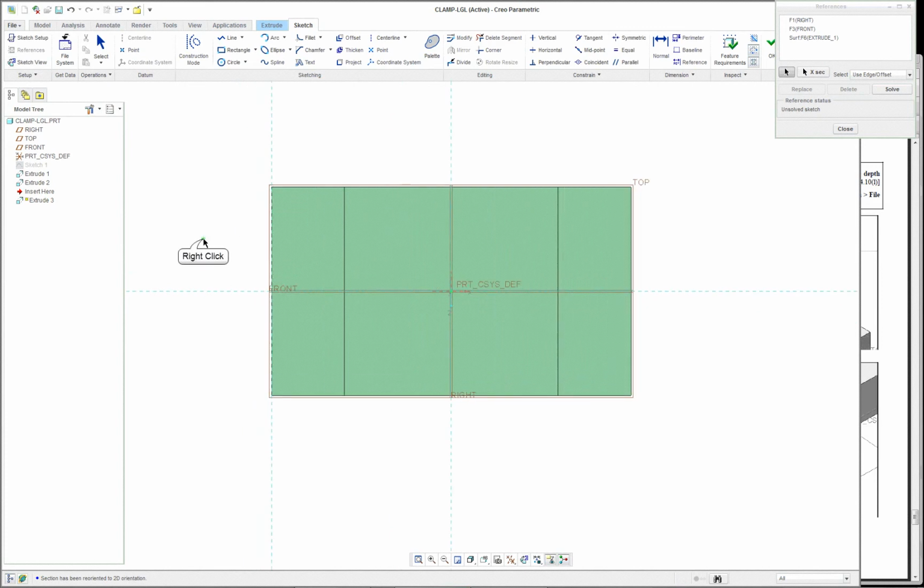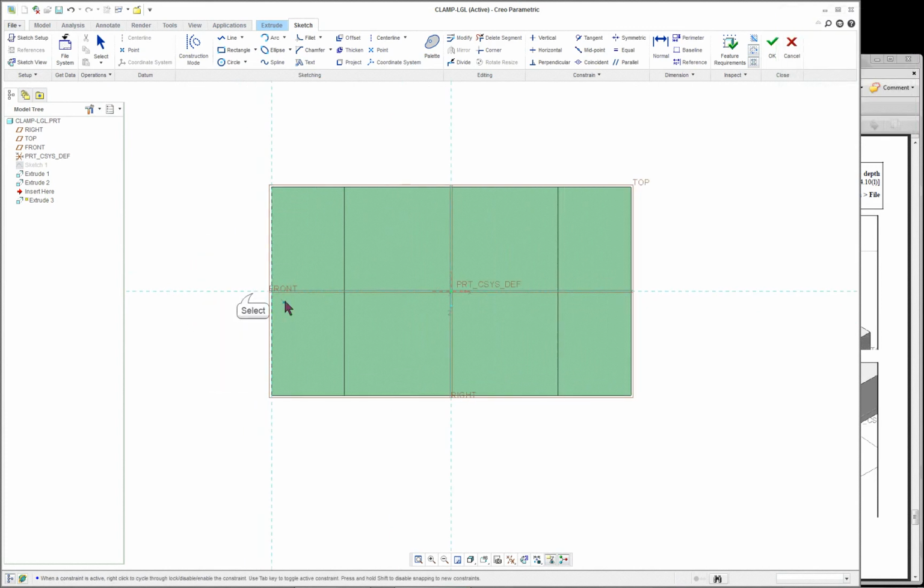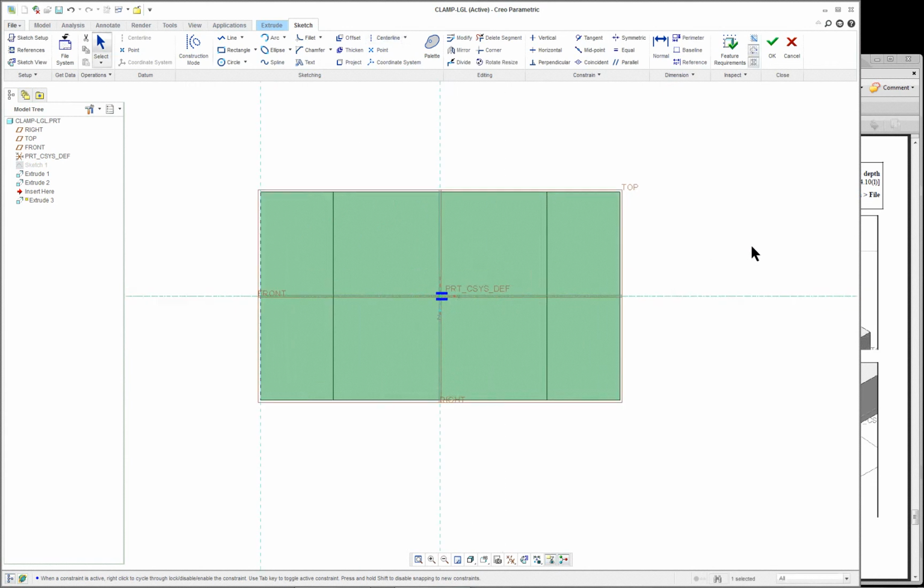So I'm going to need a center line. Right mouse button, construction center line. Middle mouse button to end it. And right mouse button, corner rectangle. And if I'm careful here, I'll get my symmetry. And you'll notice that my color choice might have been better. Green is used for other items, for instance, the constraints. Mouse button, it shaded it. And we have two dimensions.